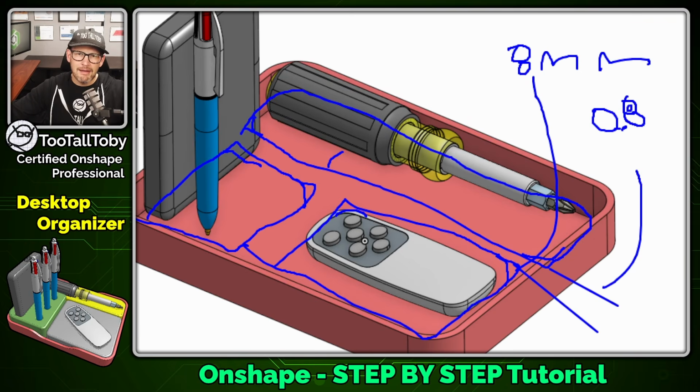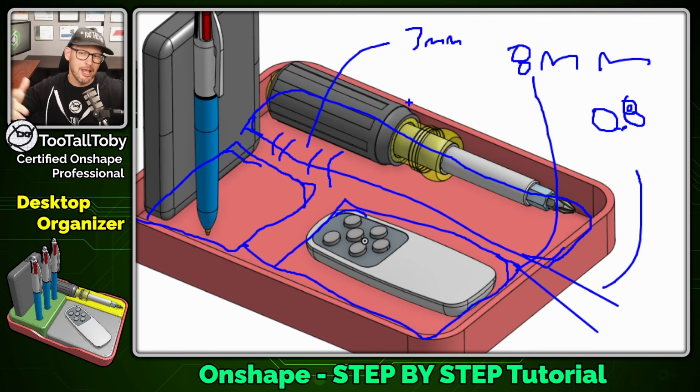And then finally, I'm going to have a little rollover fillet up at the top. I think I'll probably make that something like 3 millimeters. And again, if I decide to change that, that's fine. We can change it. But we want to be able to change it in one spot and have it affect all the parts in our document.